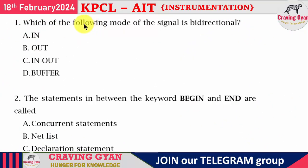In the first question, they have asked which of the following modes of the signal is bidirectional. See, this question is from HDL. In HDL, we have to talk about VHDL and Verilog. In the case of Verilog, you define input and output as input and output. But in the case of VHDL, the scenario is different. For input you define it as IN, and for output you define it as OUT. For the port to be declared as both input as well as output, you define it as INOUT. So the corresponding option is option C. This question is from VHDL.